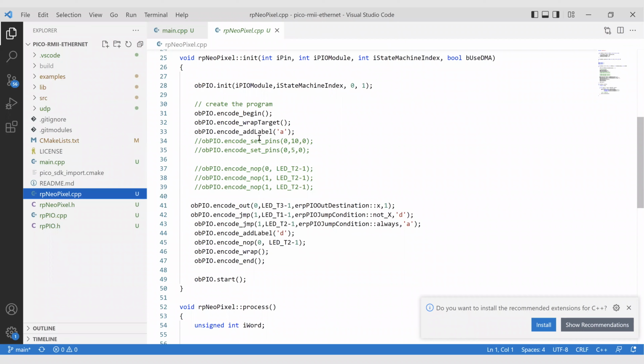What I wanted to do instead, because the PIO is so much simpler than a regular CPU, is create a compiler for the PIO inside the Pico itself. So you can dynamically generate a PIO program, which I didn't know that. Oh, that's cool. I didn't know you could do that. I thought you always had to use the little PIO assembly. Yeah, you don't. MicroPython has an implementation of PIO, which I think they also do. So it's not terribly difficult to compile. And I'll have the code for the compilation as part of the project when I upload it in about a half hour.